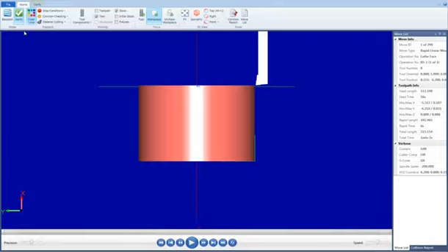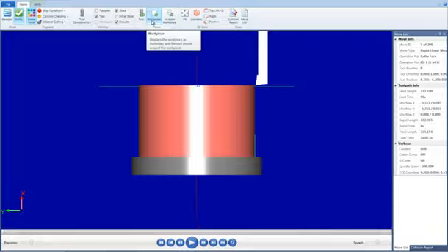Verify mode shows the path the tools take to cut the part with material removal. This display lets you spot errors in the program before you machine the part. As you verify toolpaths, Mastercam displays additional information such as the X, Y, and Z coordinates, the path length, the minimum and maximum coordinates, and the cycle time. It also shows any collisions between the workpiece and the tool. Ensure that the following are enabled: Tool, Stock, Fixtures, and Workpiece. Now select the Play button.